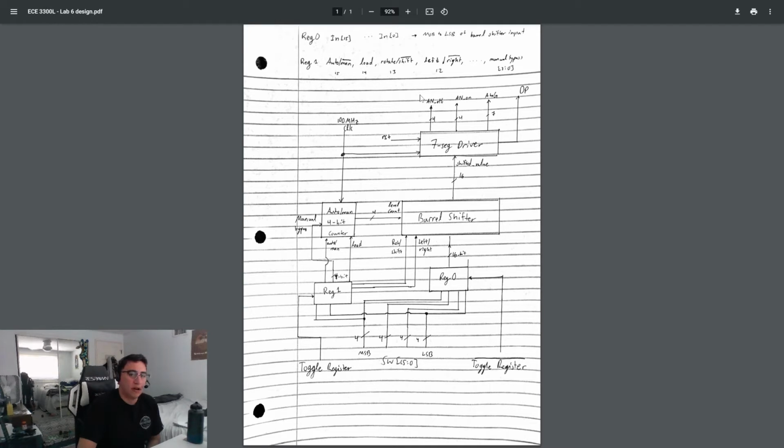So we have the 7-segment displays that are off, which is the left 4 7-segment displays. Then we have our 4 that are on, and then we have the segment values, which we want on, and then the decimal point, which we don't use. And then we have a reset, just in case we want to reset the clock divider inside this 7-segment driver. And then we have our system 100 megahertz clock.